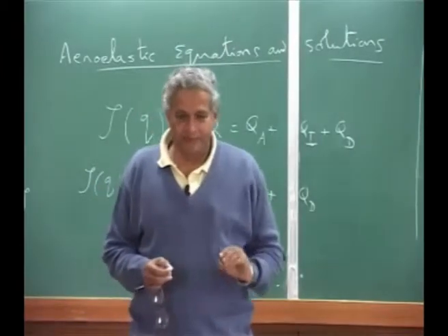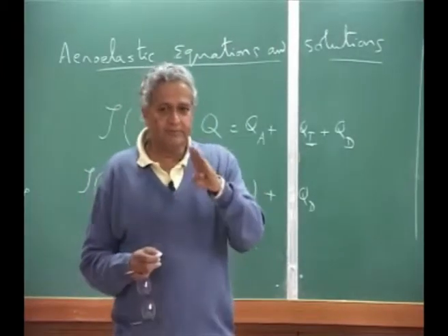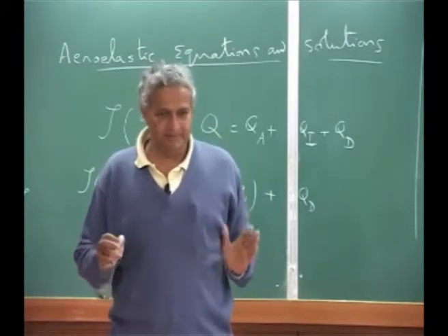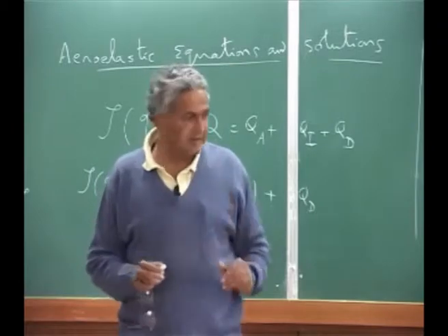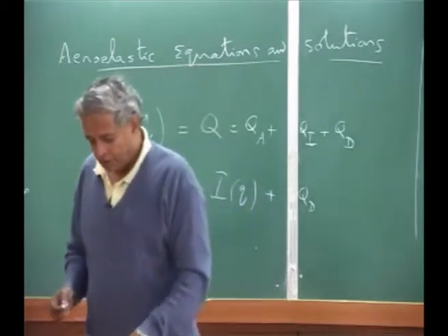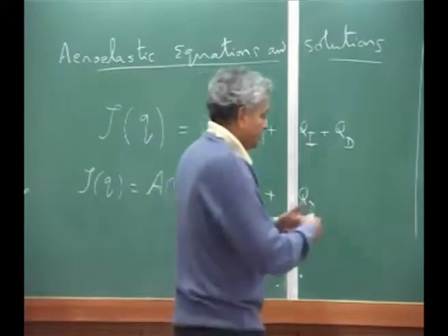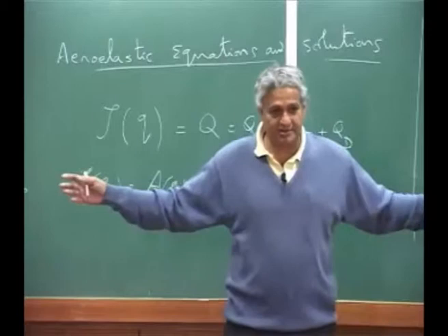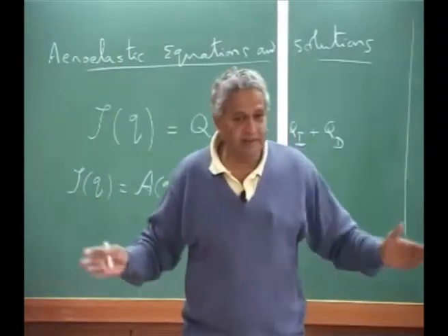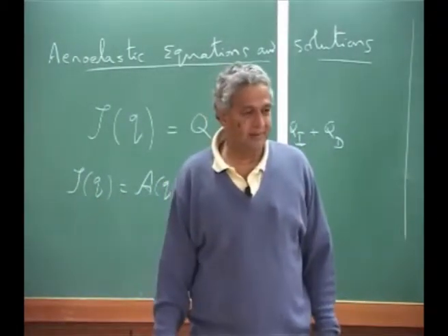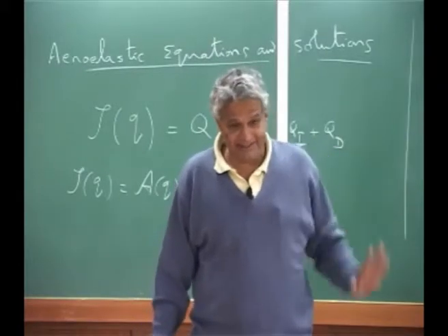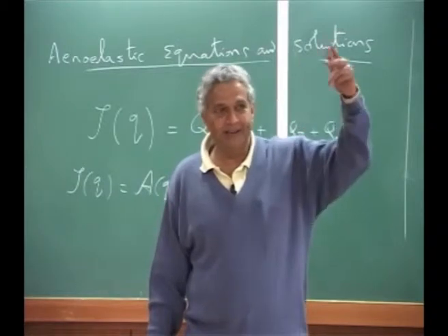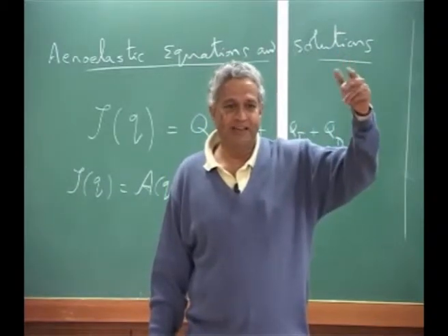Okay. Basically, I would say there are two stages involved in the solution procedure. Two steps. First step is you say that you have an infinite degree of freedom system because it is a continuous system. You are not going to solve infinite degrees. So you first have to convert the infinite degree of freedom system into a finite one.